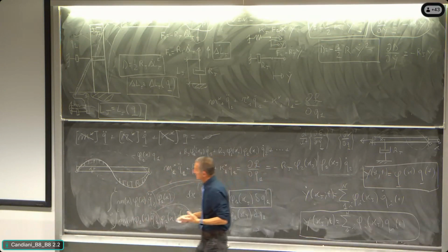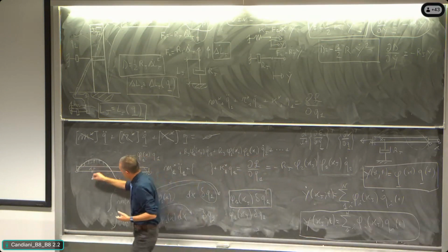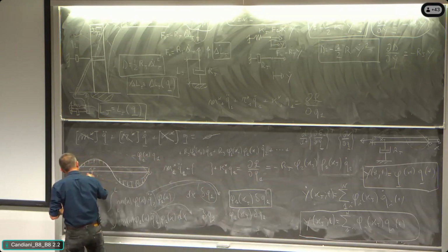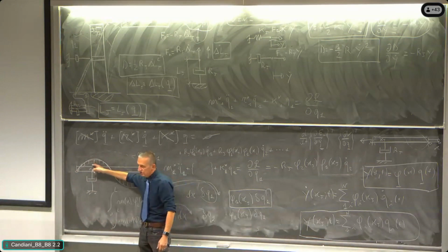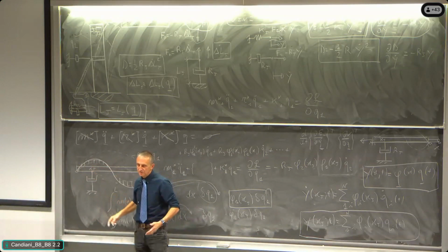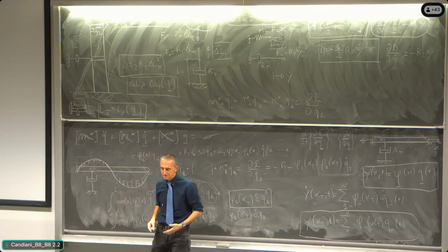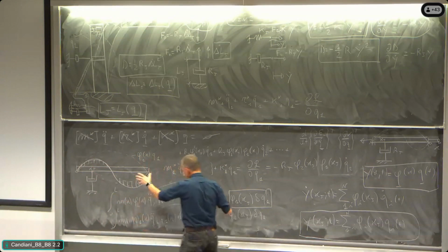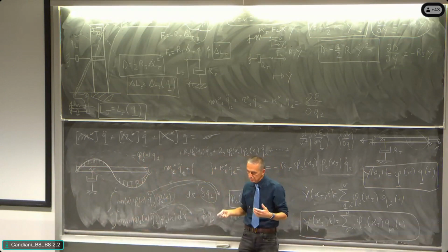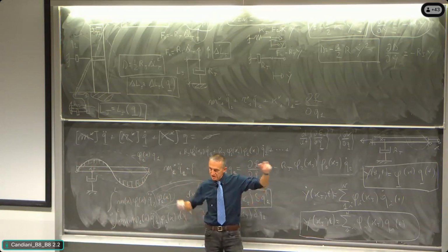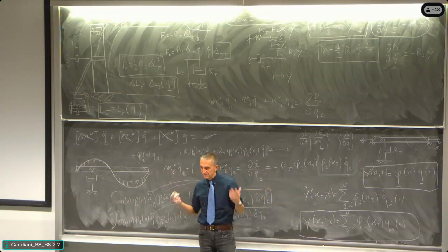It is not like here, where we are acting with a damper that is acting in one single place and we are just making the scalar product of this displacement of mode 2 and this displacement of mode 1; they are different and not equal to 0, and so they are not disappearing. So it is disappearing because we are integrating the distribution of mass through the distribution of shape of mode 1 and the distribution of shape of mode 2.